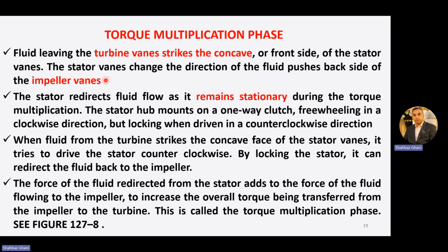Number one, the stator vanes change the direction of the fluid and push the back side of the impeller vane. The stator redirects the fluid flow as it remains stationary during the torque multiplication.